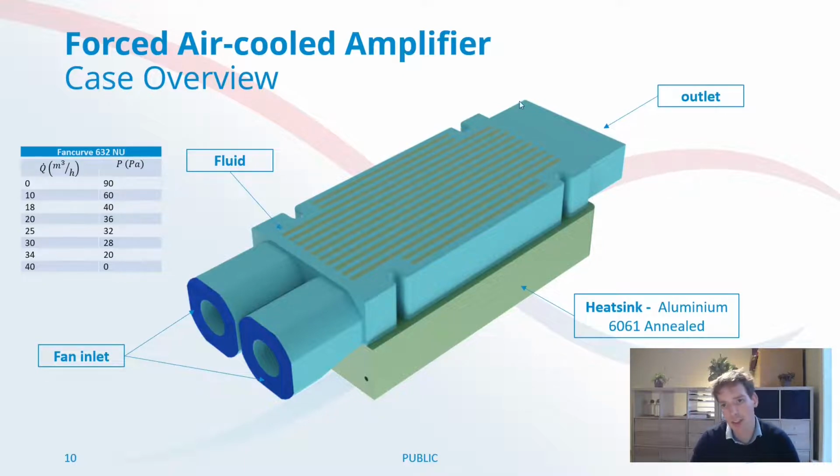Really important is at the outlet that you give the fluid a little bit more space, so don't stop right after the filter at the outlet. It's important that you give it a little bit more space to develop again. That will give you better or more accurate results, let's say.